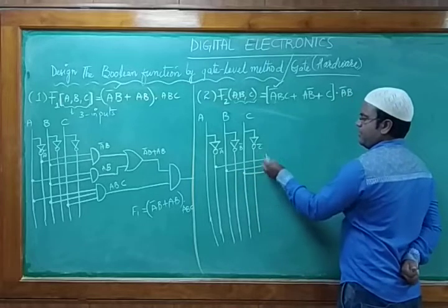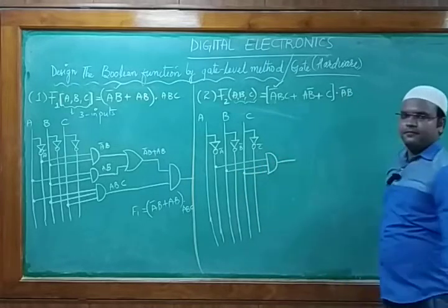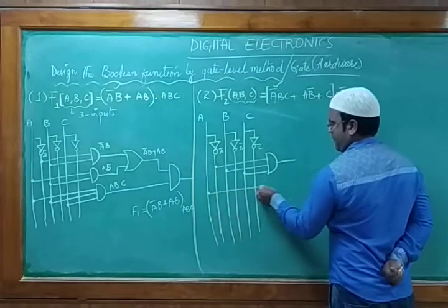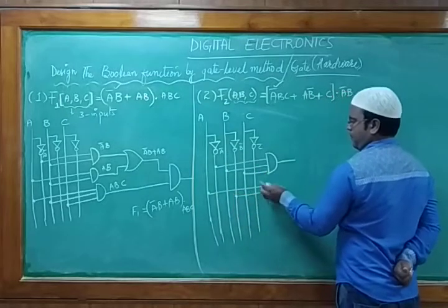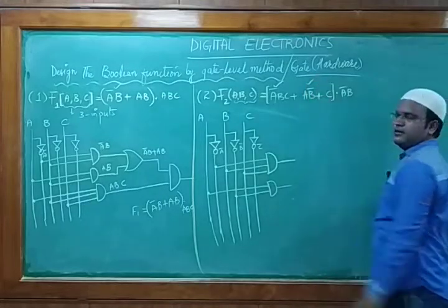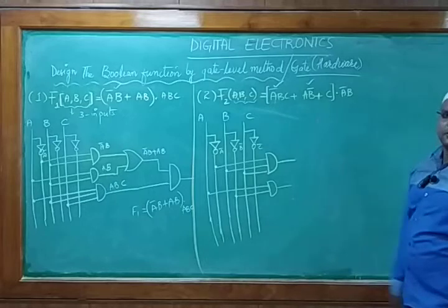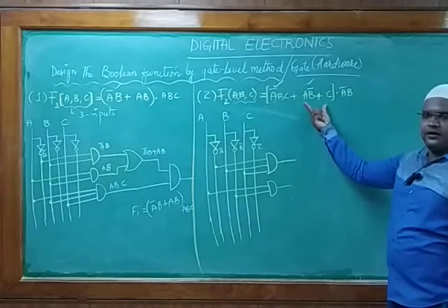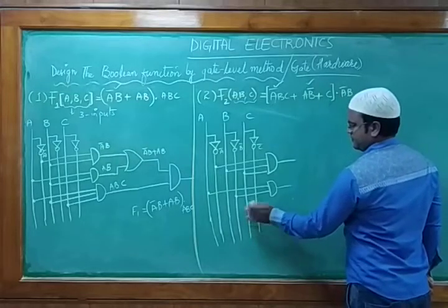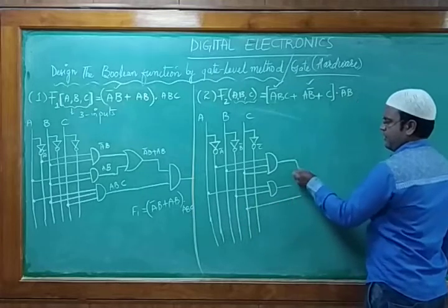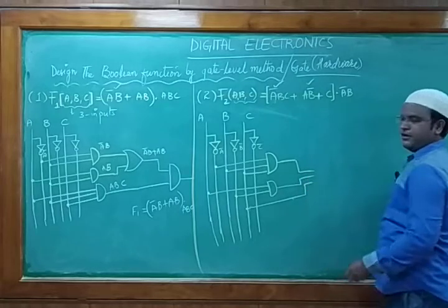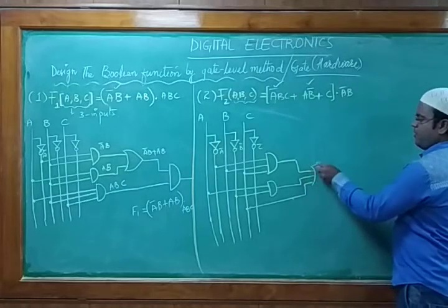So these 3 we have taken, we connect with one AND gate. Next thing, A with B bar. So we take A, this is our A value, with B bar, this is our B bar value. So we connect with one more AND gate. So this term is done. Only what is required? Plus is here, plus is here. So either way, you had one term, you had a second term. Only one more C is required. What I'm doing is taking the connection from C this way. And these 3 functions we are connecting with one OR gate.